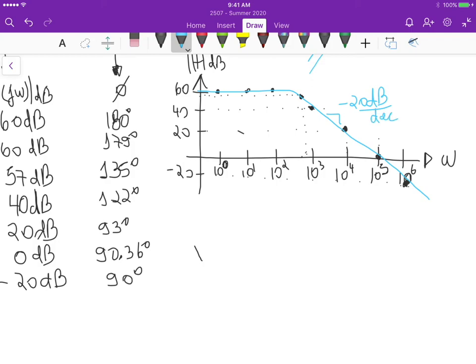Okay, so remember the difference between the first configuration that we have without the feedback resistor. In that case, the voltage transfer function would keep increasing here, right? So we would keep increasing here. But because we have inserted that feedback resistor, we are basically limiting the voltage gain at lower frequencies. Okay, so we don't go anymore to infinite dB at DC.